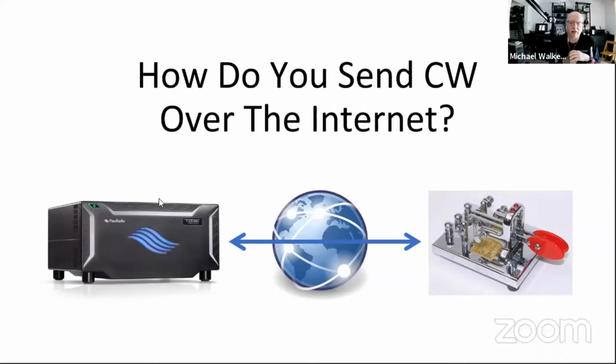Remote Rig as well has this built in. They use the same technology we use. They probably came up with it first. But I thought about this one day. So, well, how hard can it be? I just need to grab the dash side or the DIT side, or just level, RTS on the CW or on the RS-232 port and have it toggle the transmitter on and off, and I'll get some audio feedback somehow and be good to go. Well, yeah, sure. Technically, that works beautifully as long as you don't want to send more than about 1 word per minute. And I think it's the next slide.